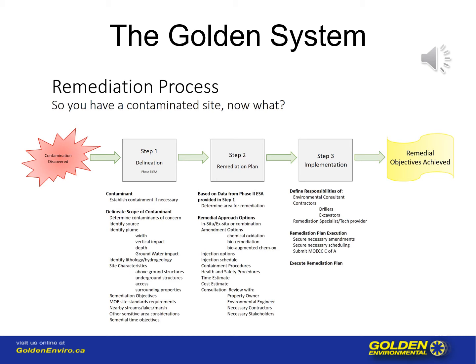Remember, during this process, occupants are able to stay inside their home during the entire remediation process. They do not need to relocate. We don't dig out underneath buildings or underpin because there is no need to. The only ex situ process that is involved is digging out the immediate impact zone. For example, where a home heating fuel oil tank has discharged its oil, we will dig out that immediate impact area, but there's no need to underpin buildings.